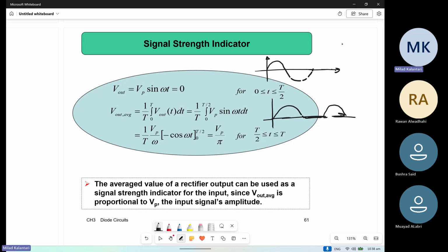So this initial signal, does it have any DC value? It is zero, right? There is no DC, because to calculate the DC, you need to take an integration over one period. The areas of the positive and negative parts are similar, so the DC is zero.